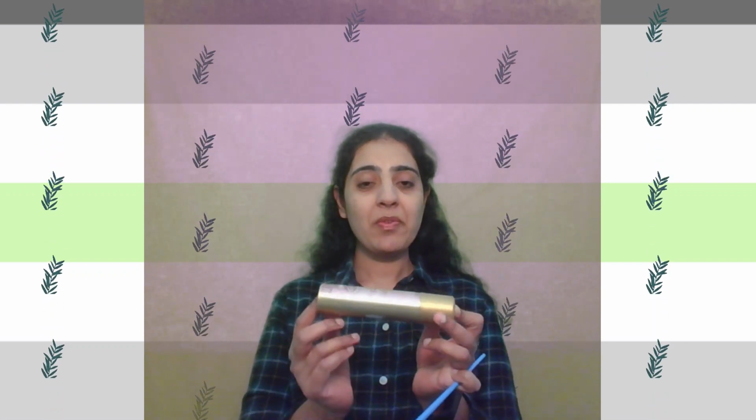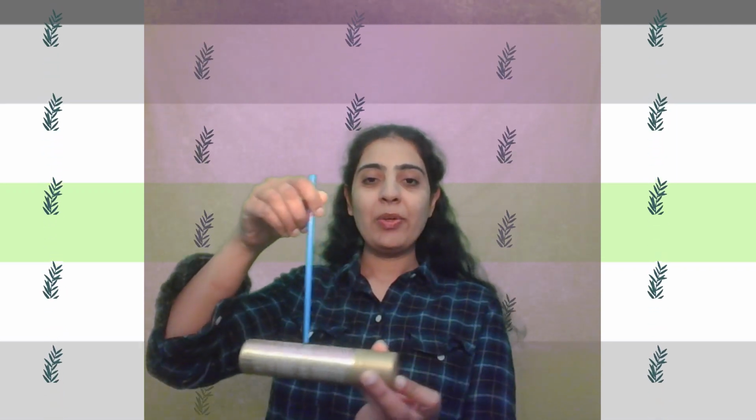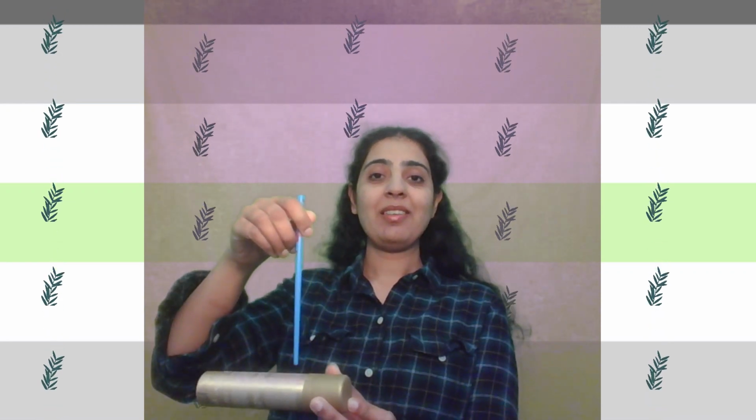Beams. In today's video and in some subsequent videos, we will study the structural element called beams. Beams are any horizontal element in a building or structure which carries lateral loads. Now, what is the term lateral loads? If this is the beam and this is the axis of the beam, the loads perpendicular to the axis of the beam are the lateral loads.